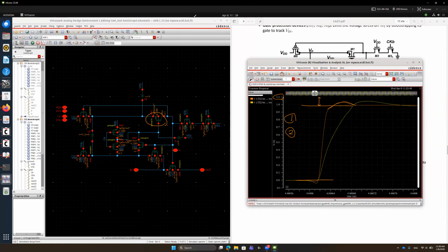this is a similar situation as we studied in the continuous time filter. It looks like it is stabilized with some sort of less phase margin, right? Because of this oscillation response.